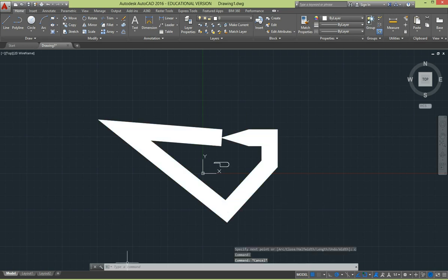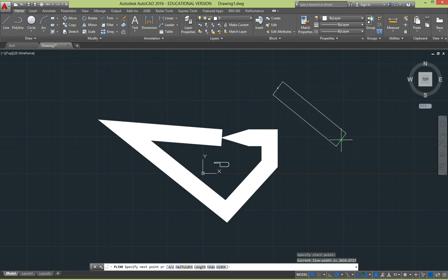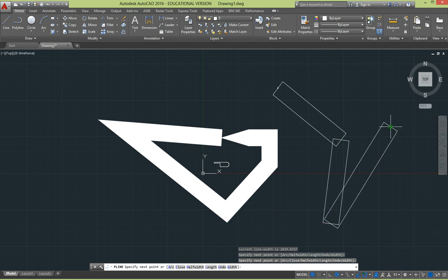Now there is a command called fill, and it is either on or off, and if we set that to off, our polylines are not filled. Let's see if it works. Yep, so that's working as an unfilled polyline. That could be useful in some cases. I'll just set it back to fill on again, and we'll go back into polyline.